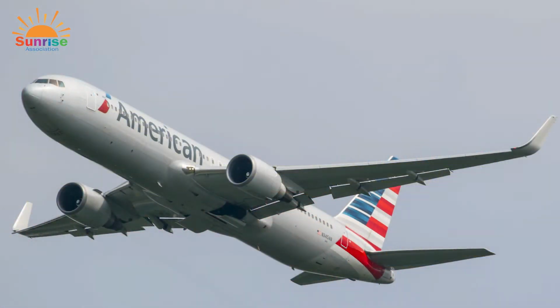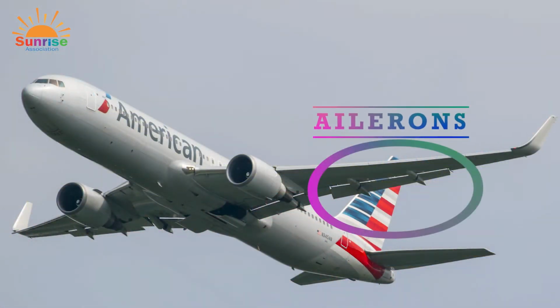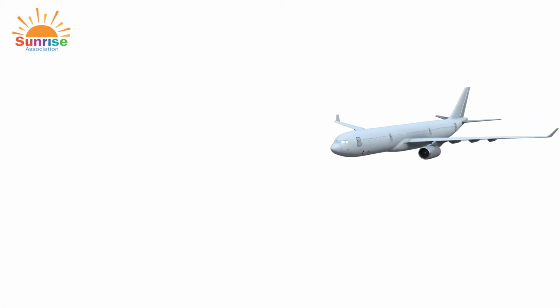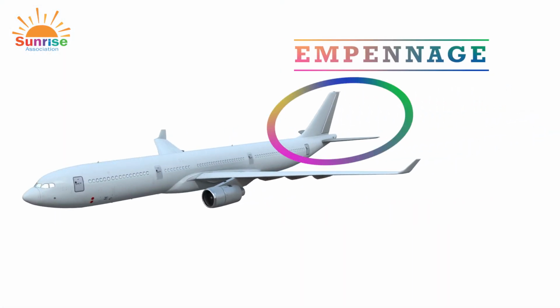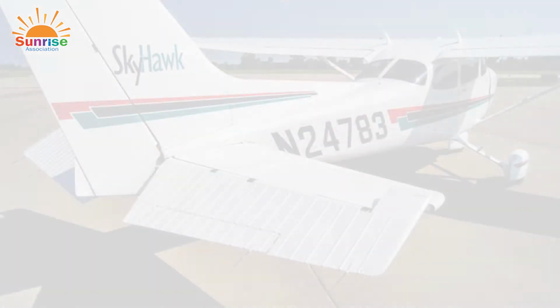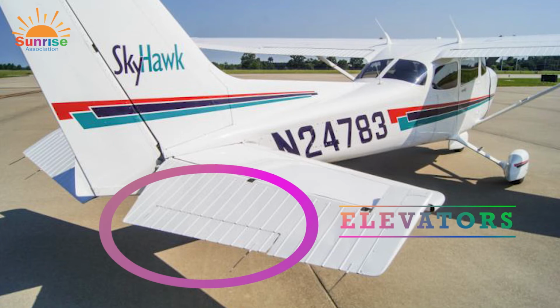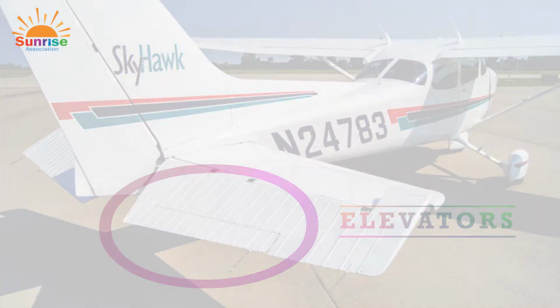At the tip of the front wings are the ailerons. They are movable parts of the wings that are controlled by the pilots and permit them to bank the aircraft for curving or turning. The tail section of the aircraft is known as the empennage. Its main purpose is to give stability to the aircraft. Found on the smaller back wings of the plane are the elevators. They are responsible for the up and down motion of the aircraft.